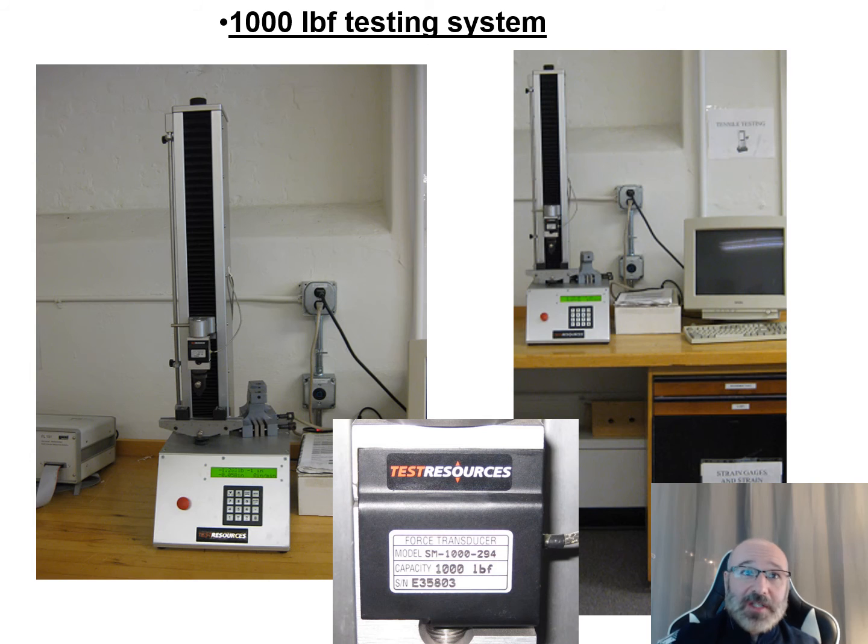Another smaller desktop version is great if we're really looking at some of the finer details, where we want to see differences of a couple pounds. Maybe that 60,000 pound machine is only going to be accurate to 10 or 20 pounds plus or minus, whereas this one right here gets down to sub 1 pound accuracy. This is another lead screw uniaxial machine that we had. It only goes up to 1,000 pounds, so it's for the lower loads, but with more accurate results.